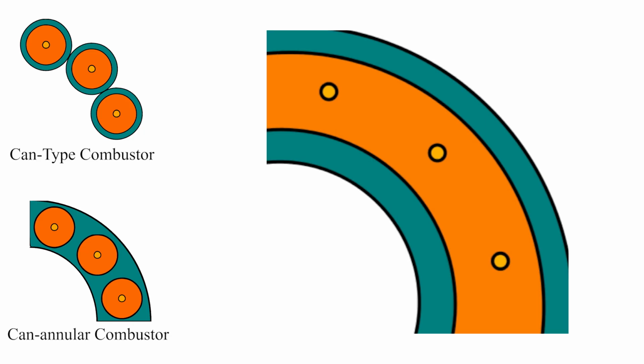Like an annular combustor, the DAC is a continuous ring without separate combustion zones around the radius. The difference is that the combustor has two combustion zones around the ring, a pilot zone and a main zone. The pilot zone acts like that of a single annular combustor, and is the only zone operating at low power levels. At high power levels, the main zone is used as well, increasing air and mass flow through the combustor.